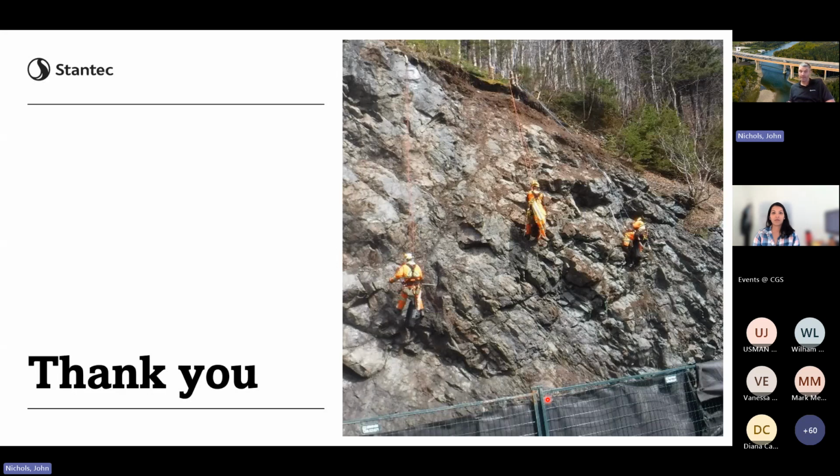A hollow core, as was mentioned, would be used in a passive bolt scenario. Those would be used when very poor rock quality is present, and you essentially do not think that you can pull out your drill when you do downhole hammer to open the hole. You think that the quality is too bad, and when you pull out, you won't be able to get your rod in. So in that scenario, we put a drilling bit at the edge of our anchor, and we drill it to depth, and we grout it from inside. So hollow core is very expensive to use and has a specific application for poor quality rock.